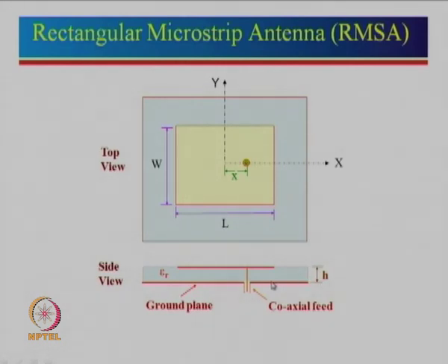It is very similar to a printed circuit board you might have seen inside your mobile phone, TV or any electronic gadget. On one side there is a ground plane of copper, then a dielectric material, and on top there is copper. If you look at a microcontroller board, it has many parallel lines running on it. But for a microstrip antenna, we just keep the ground plane at the bottom as it is, so do not etch it out.